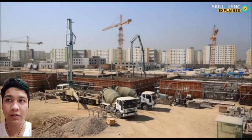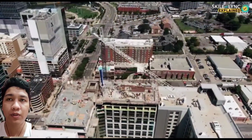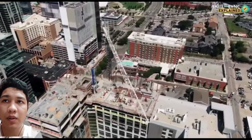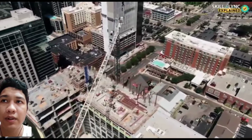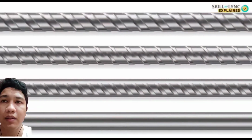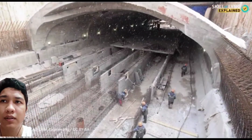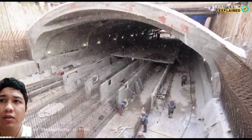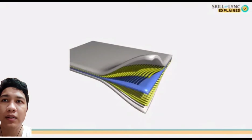To continue, it's common everywhere to notice the reinforced concrete used for constructions. But have you ever thought of the need of using it? Well, concrete is a material that has very good compressive strength, but it fails when a tensile load is applied on it. On the other hand, steel rods have good tensile strength. Now, when you combine these two materials, it gives us reinforced concrete with improved tensile and compressive strength.